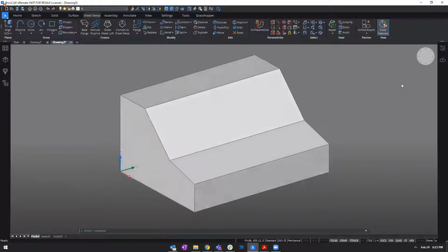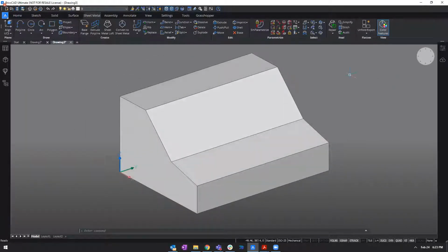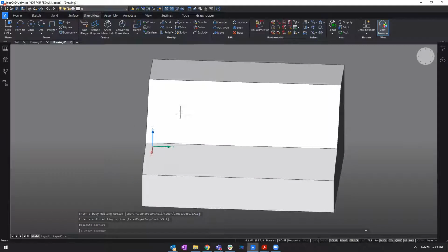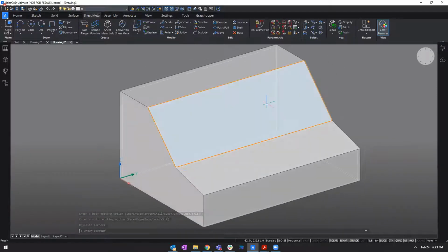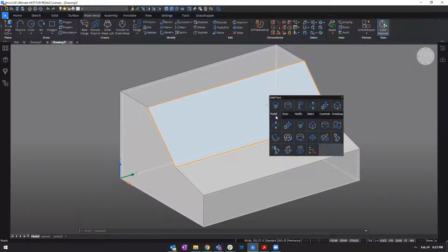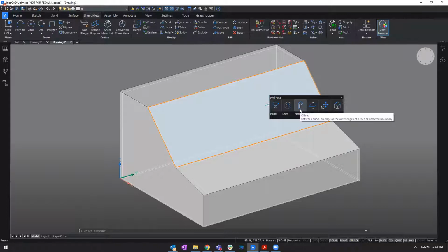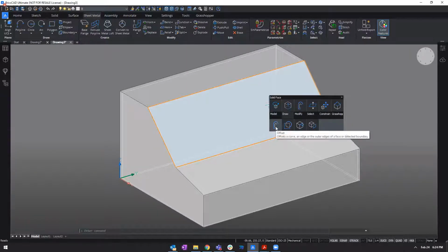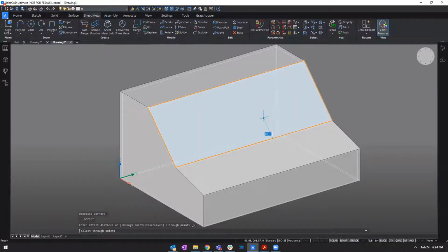Now I need to make sure that when choosing the depth of my extrusion, I don't go too deep, because I am actually creating a hole here in the back of the solid, which I don't want. So I need to go deep enough that I'm going through this face, but not too deep that I'm going through here. So something in between, like 50 millimeters or something, should be fine. And I have my extrusion here.